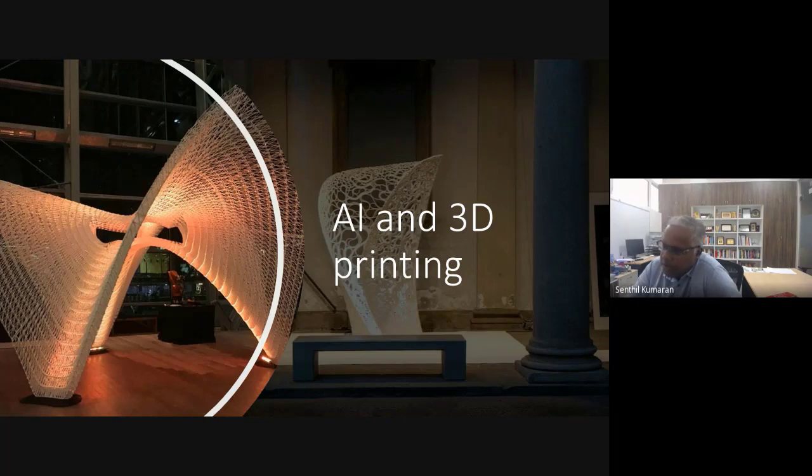So it can help you make some improved functionality over the surfaces. It's possible. It can be done, not a problem. But PVA, I'm not sure, but you can do it on TPU, PLA, and ABS. You can give a hydrophobic coating, which can help you have an improved functionality. This is what is functional integration. You can take any functional aspects of it. For example, you want flame retardance, electromagnetic interference shielding. So you can add any function you want. You can add acoustic functions also, things like that.